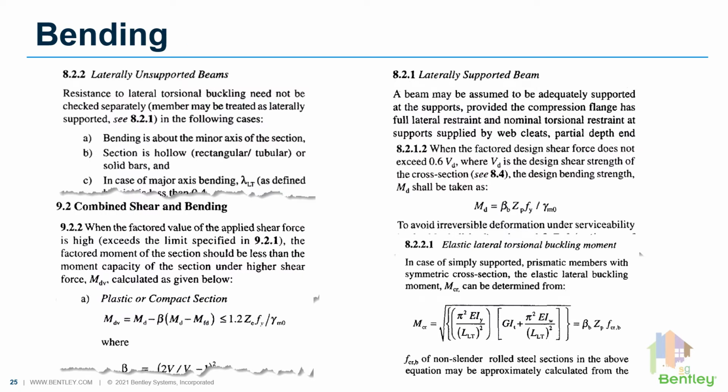For bending capacity, the design provisions mentioned in the IS800 code are not properly clarified. The code suggests design rules for individual and general cases, but for specific cases like a web slender section, how to consider the clauses is unclear. I will discuss this shortly and also let you know how we interpret the clauses and how it is implemented